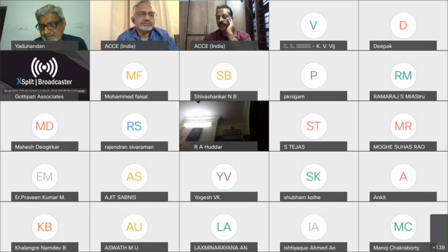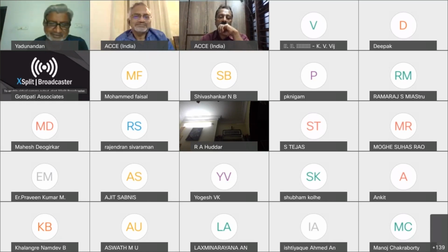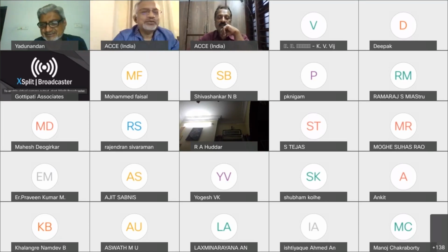Okay, sir, I am giving higher depth beam in one direction and lower size beam in the other direction. Is that okay, or do I need to give beam depth equal in both directions? Which solution is better, sir? The shorter direction beam you have to take the deeper one. Yes, sir. Okay, thank you, sir.